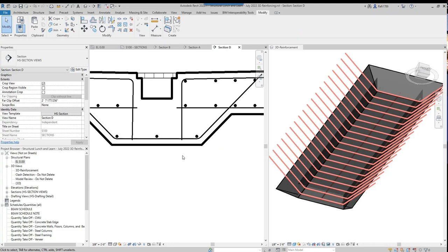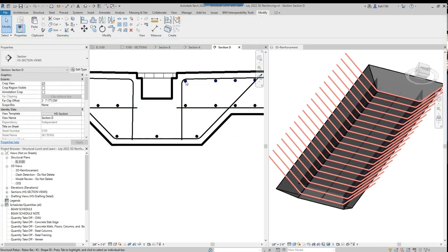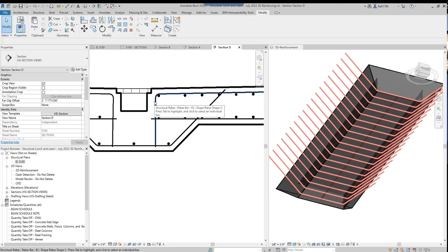Hey, Raphael, is there a way to bend the bars up at the top to run parallel? Those up at the very top where they go up on an angle, but then they just never kind of align with the rebar running up the slope. Hold on. Start over with your question again. So you see where they run up the slope right into the floor reinforcing, and then up at the top, I get comments that those need to be bent to run parallel with that top reinforcing.